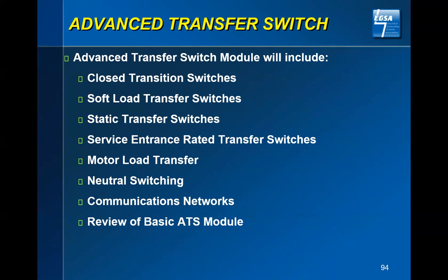We'll look into a little bit more modal load transfer. I will tell you that neutral switching is either you have a solid neutral or a switched neutral. If you want to research that a little bit, get into the National Electrical Code and look at what is defined as a separately derived source. If I have my utility coming in and at my main gear I am taking my neutral to ground and making my ground reference there, that gives you the 277 volts off of a 480 volt feed.